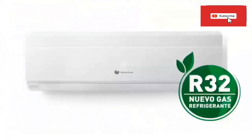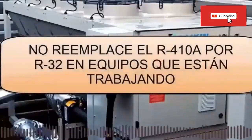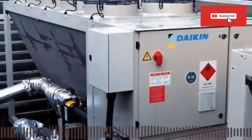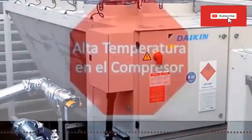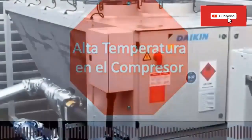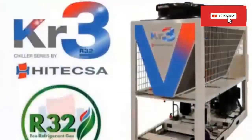3. A system that was originally designed for R410 will not have taken into account the safety factors required when using an A2L refrigerant such as R32 and could create a significant safety hazard. This means that R32 should only be used by manufacturers of new air conditioners. 4. The discharge temperature of the compressor, which works with R32 refrigerant, is high, so the heat recovery option can be used.